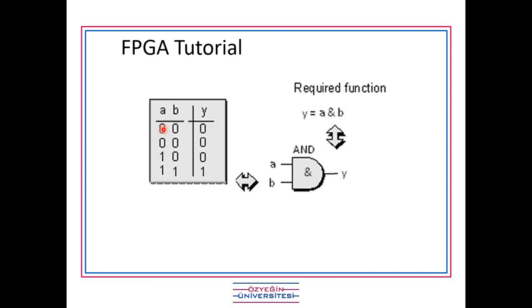You just have to provide inputs, and it will give you outputs. So it's kind of imitating what the actual hardware is doing. But inside the hardware, we have this, but this is actually what we had in mind, and the synthesizer changed what we have written into something that the FPGA can understand, which is the LUT.